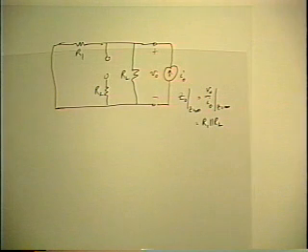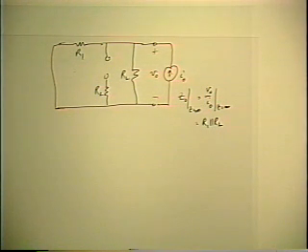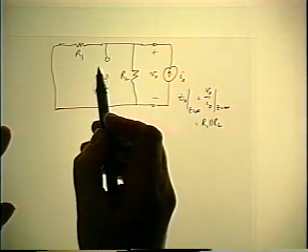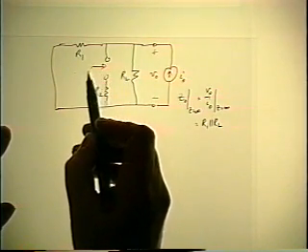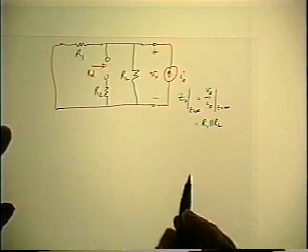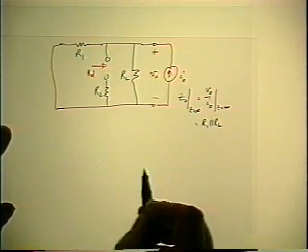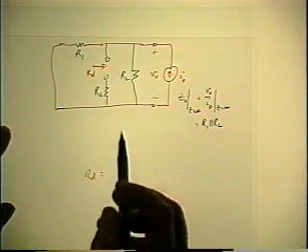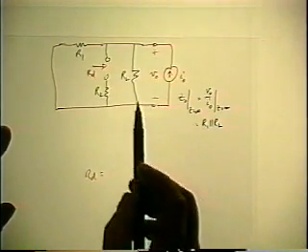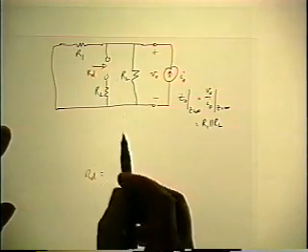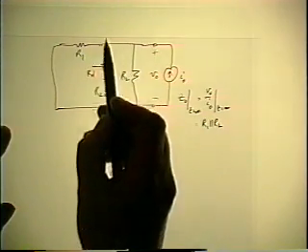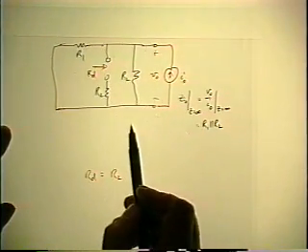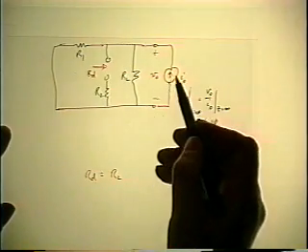Now we have to calculate two driving point resistances. So first we look in where the element is going to go, and we want to calculate R_D. So R_D is a single injection calculation: the resistance looking in, which is R2 to ground in this direction, and in the other direction R1 parallel R_L, because the input is going to be 0.